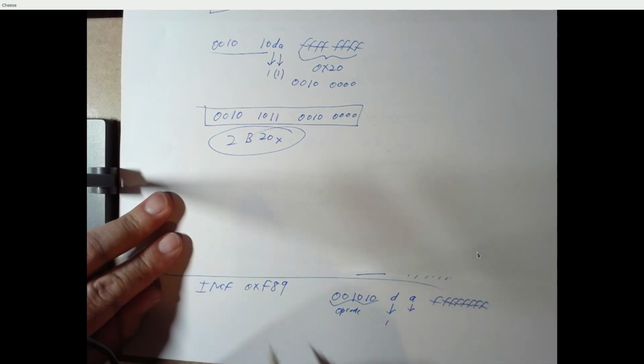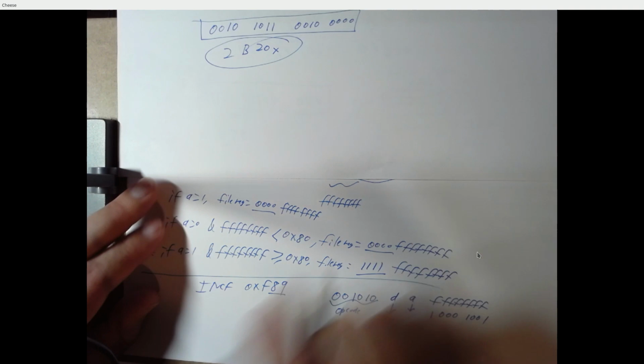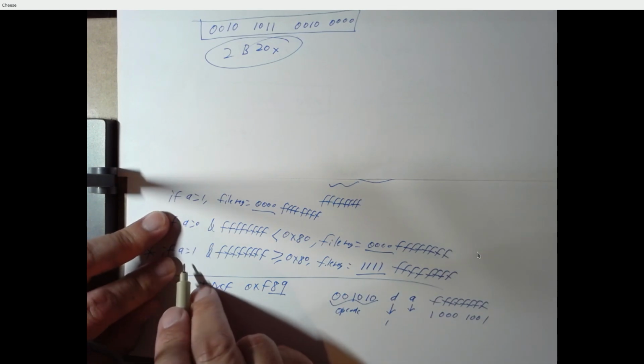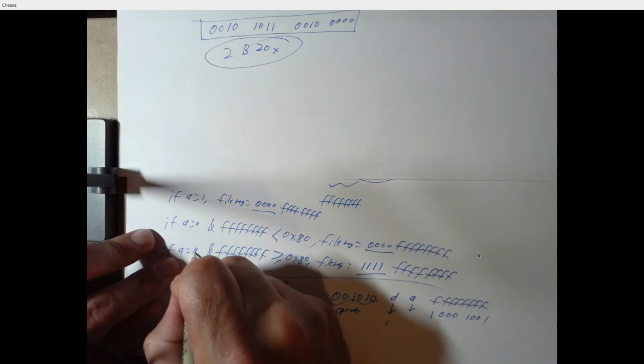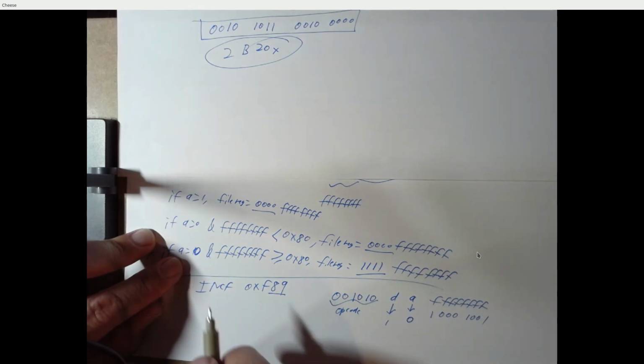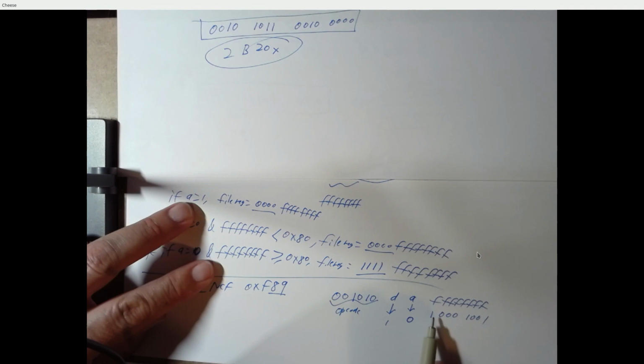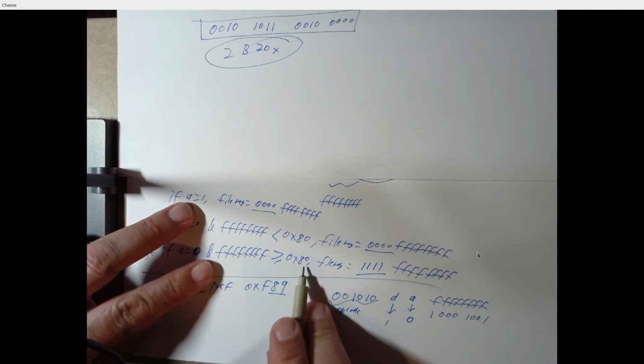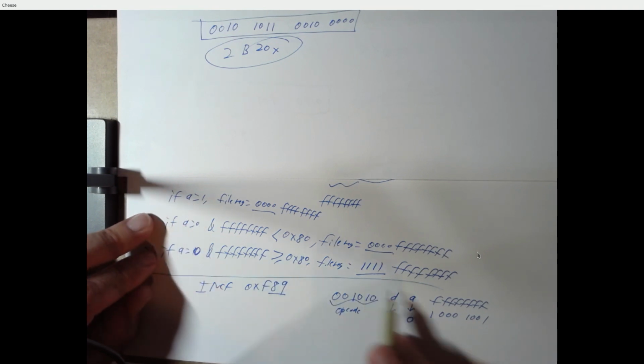since we can only specify 8 bits, we're just going to specify the last 8 bits. This is going to be hex 8 and hex 9. But our access bit, if we set our access bit equal to, sorry, this is a 0. If we set our access bit equal to 0, since our 8-bit number is bigger than or equal to hex 80, this is going to prepend 4 ones to our address F. And so we're going to actually be specifying location F89.